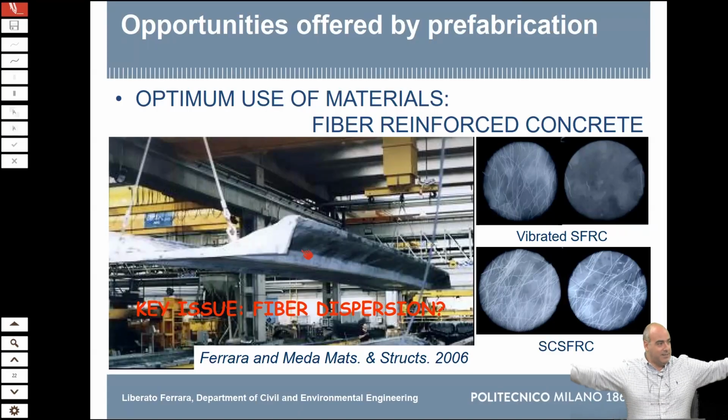But the other thing is that these two wings work as cantilevers. And when you install this side by side, for example, here you lay out a roofing, sky roof. So you have some concentrated forces acting exactly here. So that cantilever is subjected to a point load at its free edge. So you have negative bending moment here where this cantilever wing frames into the main bulb. Negative moment, what does it mean? It means that you need reinforcement on the top.